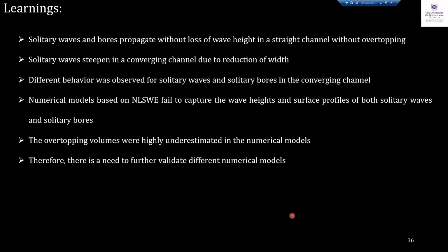So these are the key findings from this modeling, that when solitary waves and bores propagate into the convergence, they're gonna steepen or increase in wave height. And then the behavior of waves, non-breaking waves, is different from breaking waves. The nonlinear shallow water equations cannot capture the phenomena that we see in the lab. And the overtopping volumes were highly underestimated in these 2D shallow water equation models. So I did further modeling with 3D models, which I'm not showing here.